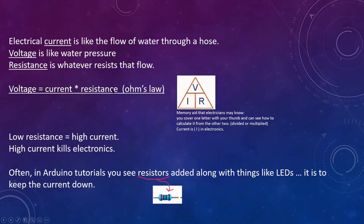That's not necessarily an equation you have to memorize, but it is an extremely important one. It's called Ohm's law, and it's so popular they've come up with neat little mnemonics for people who don't want to remember the equation. Basically, in electronics, I is current, so you can put your thumb over the V or over the R and it will tell you how to get that particular element. So if I cover the R with my thumb, it says V over I, so voltage over current equals resistance. Or if I cover up the V, then current times resistance equals voltage. So it's a neat little mnemonic that they use.